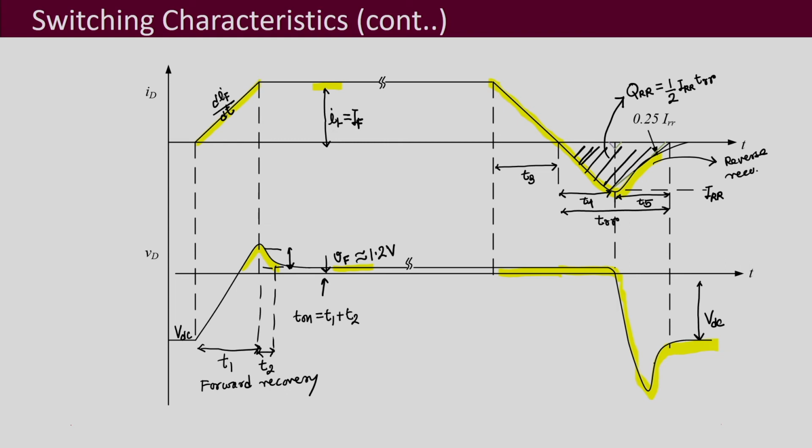and this plays a very important role in selection of diodes. Now what happens is that the on time is usually smaller than the off time for a diode. And when you select a diode, it is the off time which plays a more important role than the on time, because your off time is the deciding factor for your switching frequency.